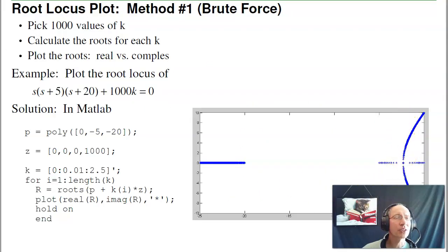So this describes how the system behaves. This is the root locus plot. And kind of the oddity, this point right here, this is equal spacing in k. Well, log spacing, actually equal spacing in k. Right at this point, if k varies just a little bit, the poles shift a lot. We're going to be using that feature a little bit later, to calculate the breakaway point, this point right here. The sensitivity becomes infinity.